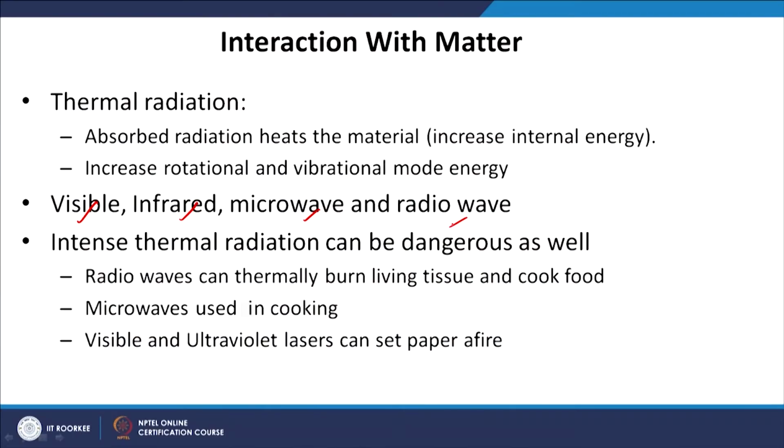When absorbed within the matter, they increase the internal energy of the material, and that is why they are called thermal radiation. The increase in internal energy is attributed to rotational and vibrational modes of energy, which get excited. The rotational modes may get excited when radiation is absorbed, vibrational modes may also get excited, and these internal modes when excited absorb or emit radiation.